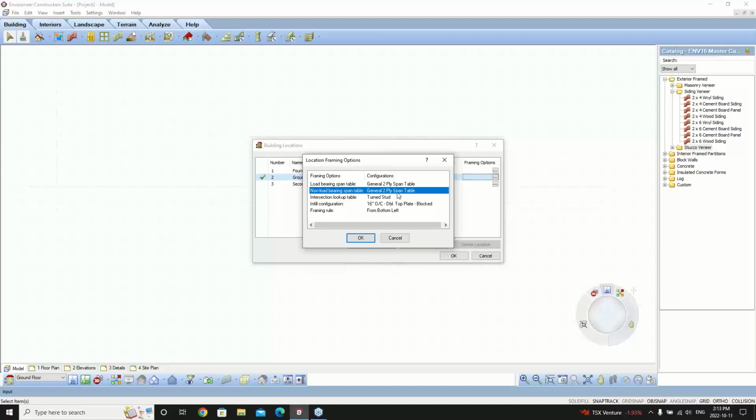You can adjust it after it's been inserted. So once you've inserted your walls, you can select those intersections and say, I want to change the style of configuration for that particular corner configuration or that intersection. So that's something that's done in the drawing after you've inserted your walls.